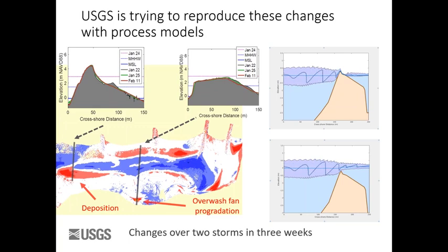In these two cases, the flux of water is actually not constrained. It doesn't just pile up against the shore. So normally, if you've got a beach and the water is setting up against the shore, that's what generates the undertow, right? Because there's got to be a return flow. You're forcing water against the shore. It's piling up, and that causes a return flow somewhere. But if you let water flow over the top of the barrier or under the backside, you don't constrain that anymore, and the elevations change, and that allows the net flow to be kind of more positive along the beach face. So it's not really the topic of this talk, but it's something I thought I'd show.